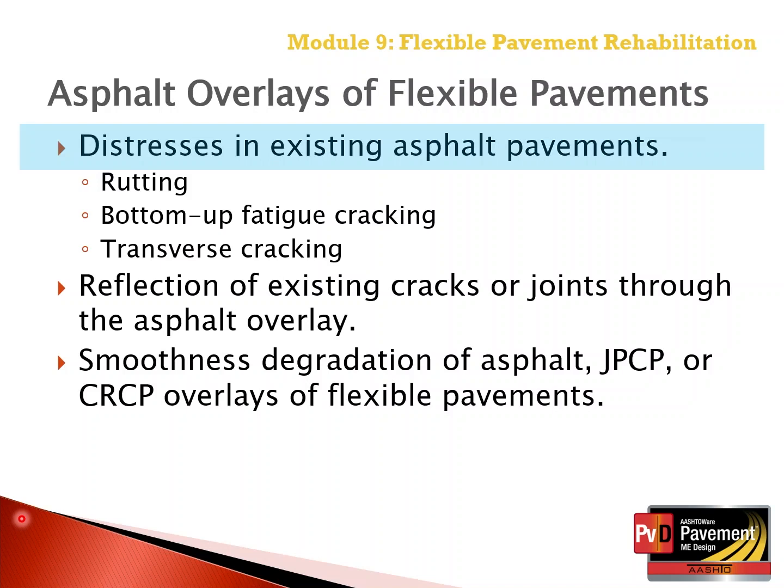This specific part on distresses in existing asphalt pavement will also review 3 distresses, how they are considered in the Pavement ME design software, and how they might differ from new flexible pavement design. First is rutting, then bottom-up fatigue cracking, and then transverse cracking.